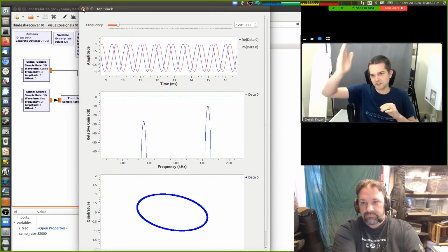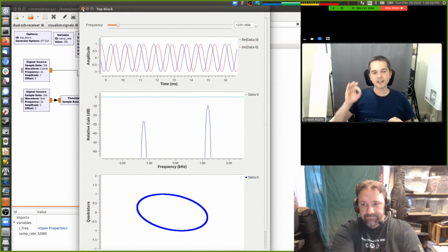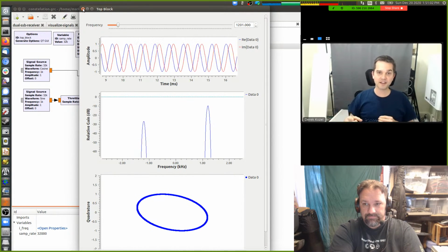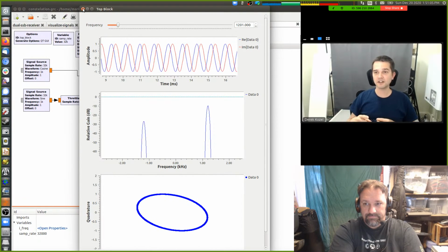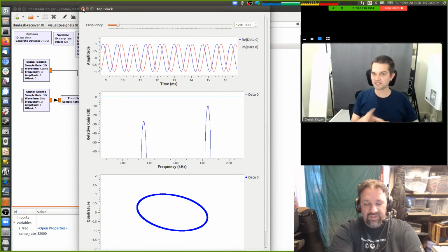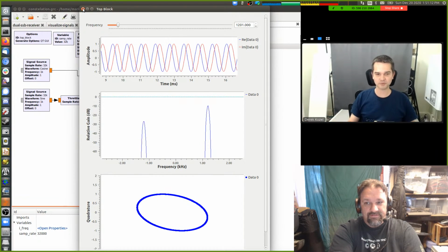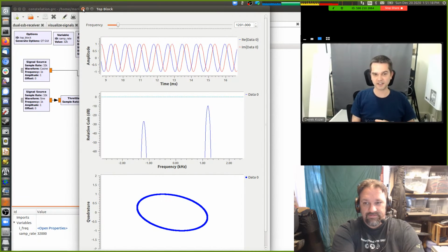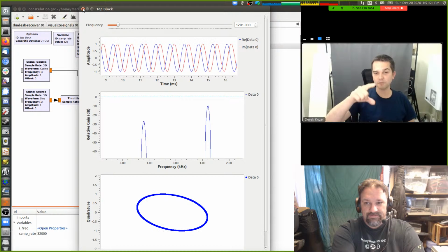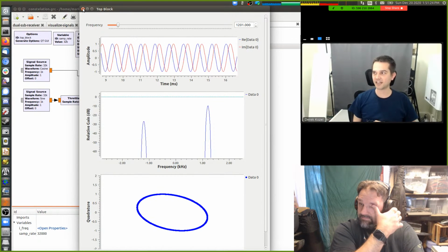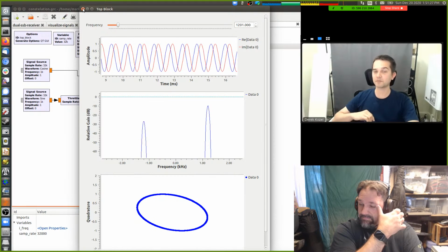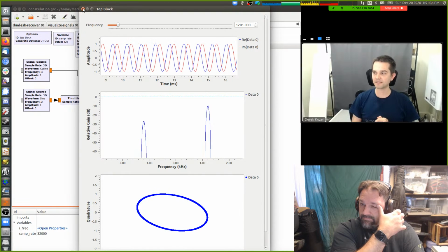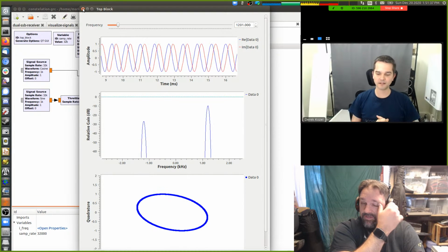We've just said there's energy here, there's energy here, and there's energy here. If you are running out into a mixer, then it is beneficial, and I'm not going to say necessary, because this is where I'm going to get trapped, and hopefully somebody in the audience would know better, but it is beneficial or possible to put a quadrature signal in and get what we saw, where we got a single sideband signal out, because we had presented the I and the Q that only gave the positive answer when mixed. So yeah, you definitely don't need it.